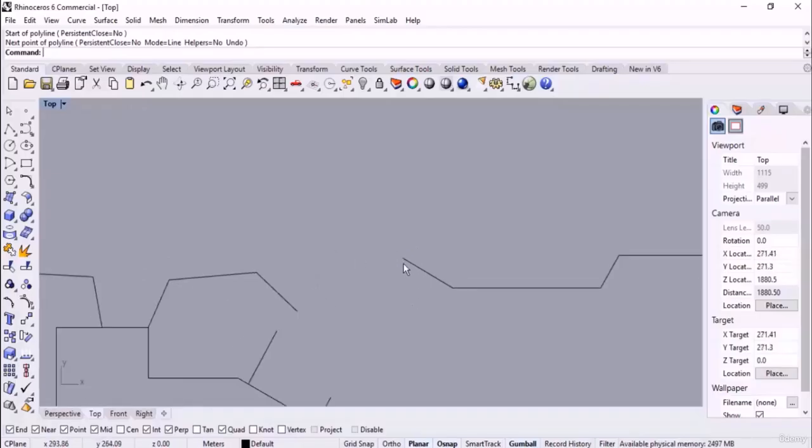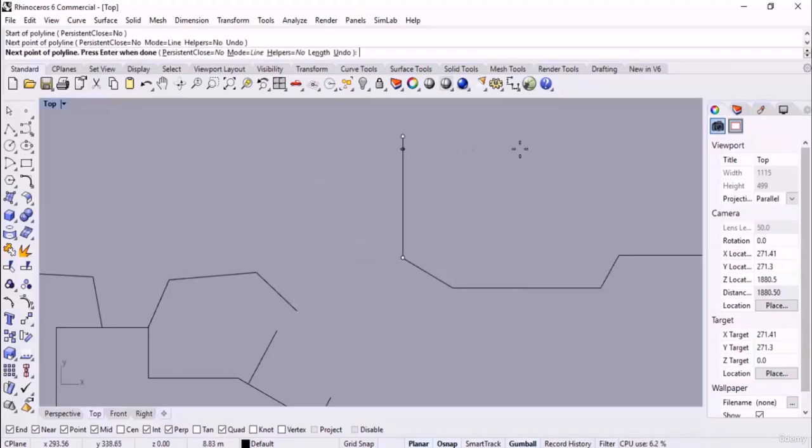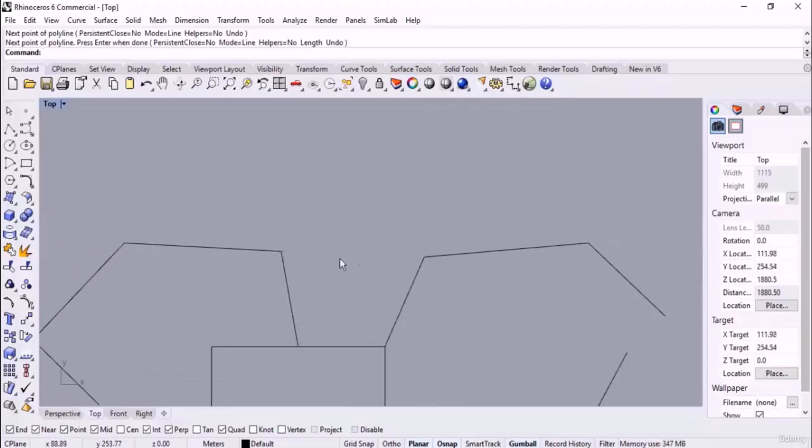Another example, for example, I want to sketch a line at this size or at this length, but at a different direction. I sketch it, but I do not click. I hold the marker, and then if I press tab to restrict the direction and length, after that I can specify the direction by this way. And I release shift to sketch the line. So by this way we can measure a distance and then associate it to the line.